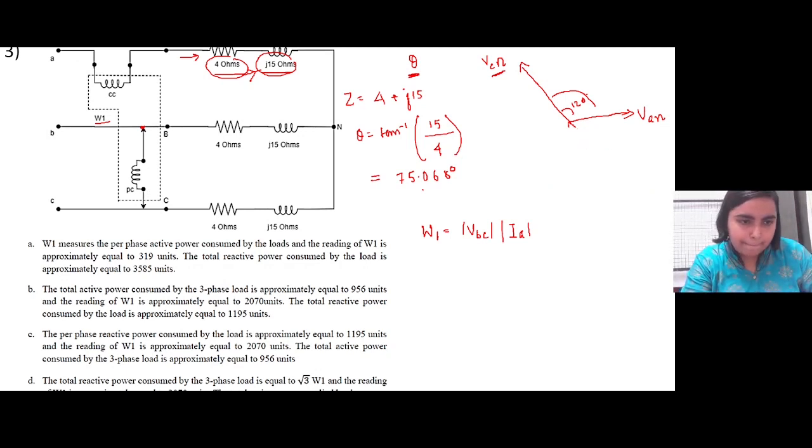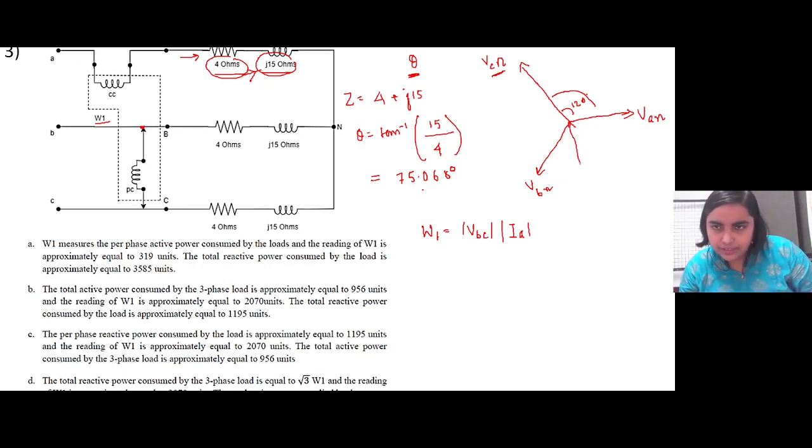So these three are the line voltages. Now, the phase voltage is common. VAN, VBN, VCN are phase voltages, right, ma'am? Yes, these are phase voltages, and VBC is the line voltage, from B line to C line.